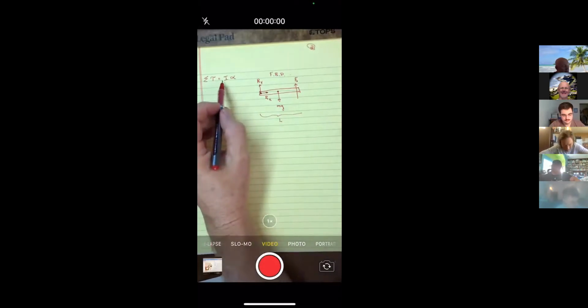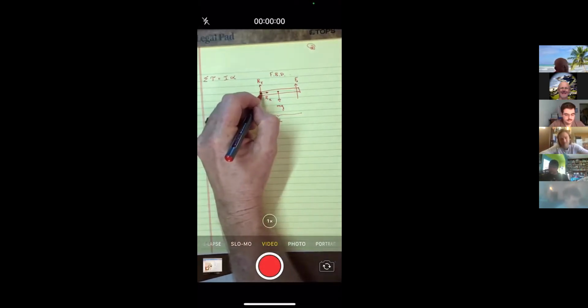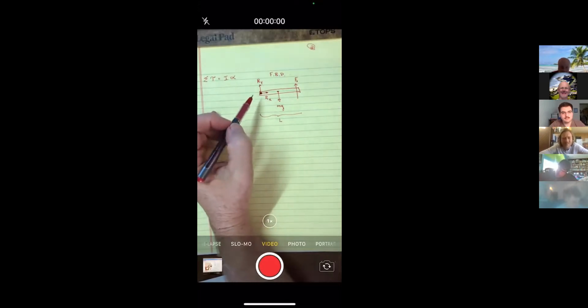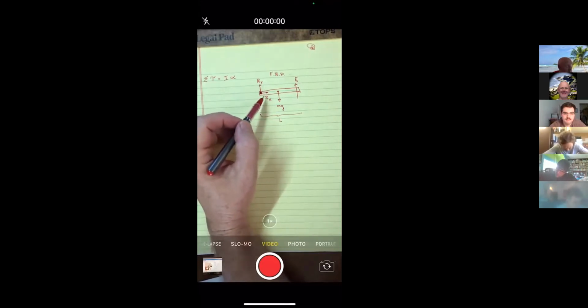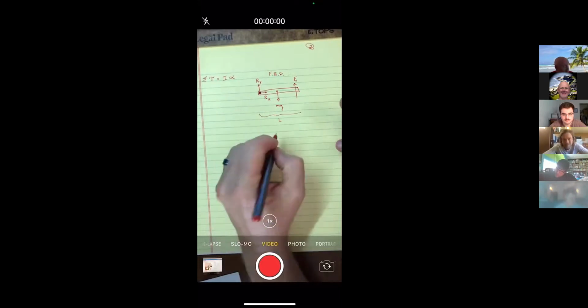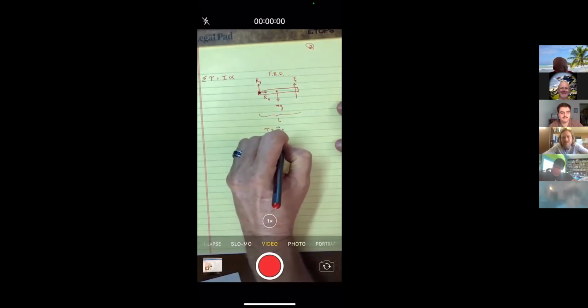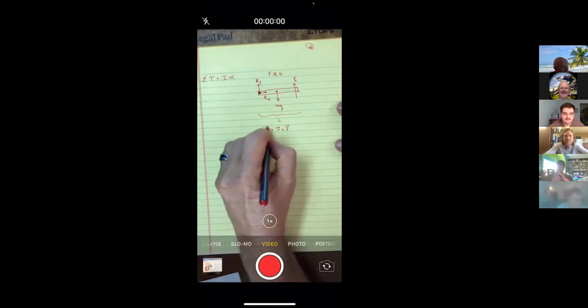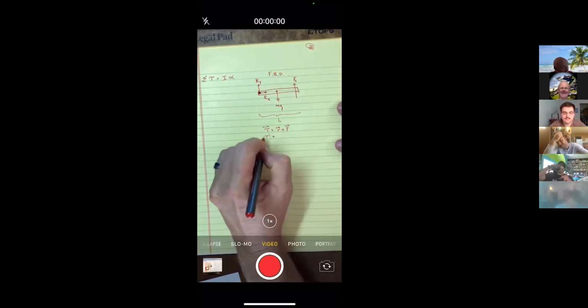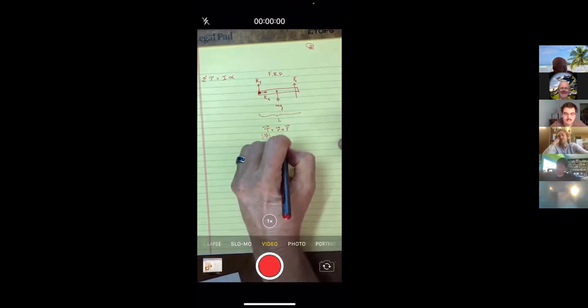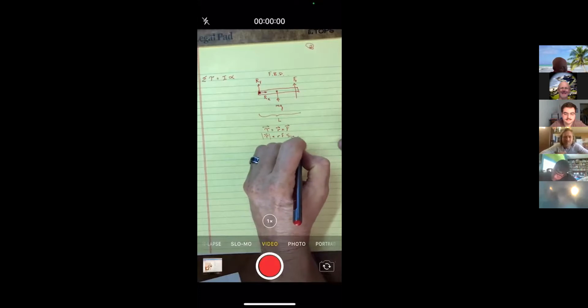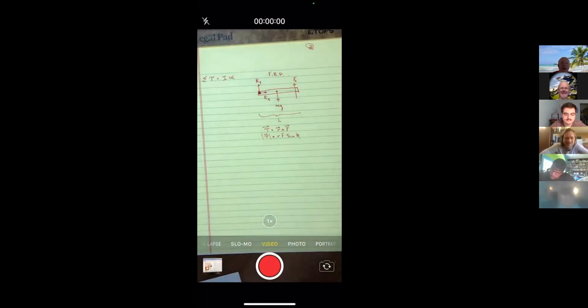So when we go to add up all the torques, we'll do the torque right here where it pivots. And again, just to remind you of Physics 121, the reactionary force then gives 0 torque, because torque is R cross F, which in terms of magnitude would be R F times the sine of the angle between R and F. I'll call it a phi, because some of these problems can have multiple angles, and phis and thetas always get confused.